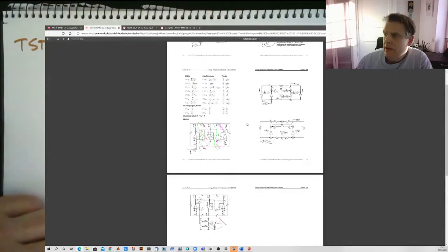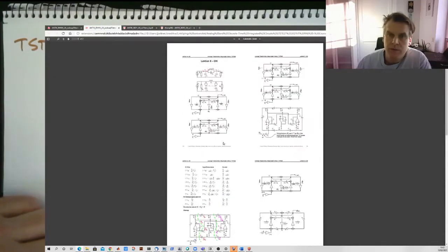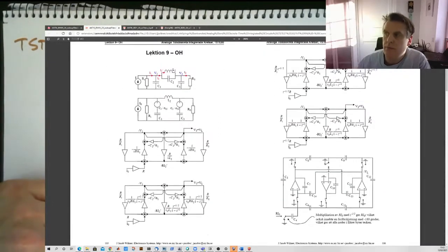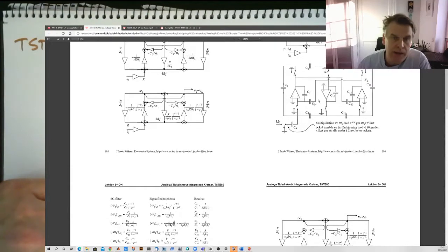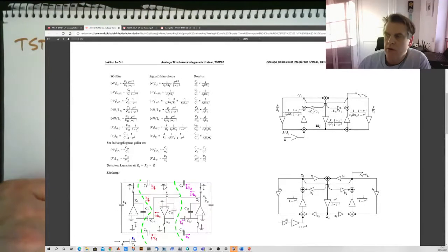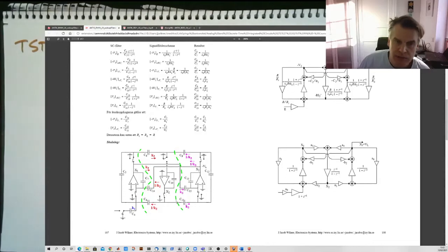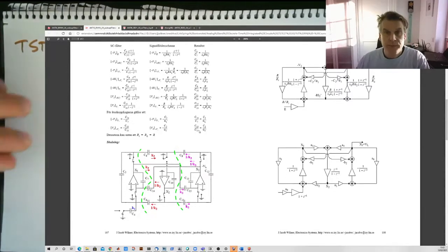All right, and then we're essentially going to do the steps which you hardly can see in the camera at the moment, but we're going to do a sort of trip from a reference filter, include some signal flow charts, do some manipulations, explain those manipulations, and then boil down to the implementation with 3 switch capacitor accumulators here. And that's the filter you're going to simulate in the lab and the project. And then we're going to look at some ways to find the values and do some potentially slight modifications. So that's where we're going to land today.